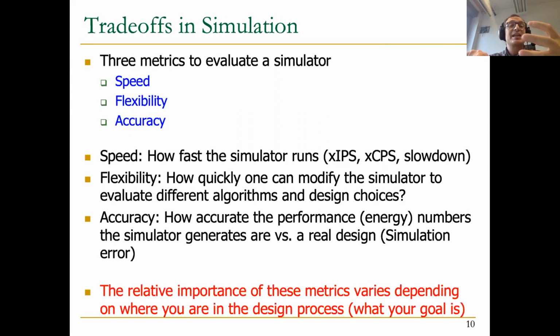And if you have a golden functional simulation, you know that you're on the wrong path whenever you're simulating in the timing simulator. So the timing simulator is on the wrong path. The functional simulator is on the wrong path also, because the branch predictor mispredicted things. But you know in the functional simulator that you shouldn't have gone that path, okay? Now this is very important.